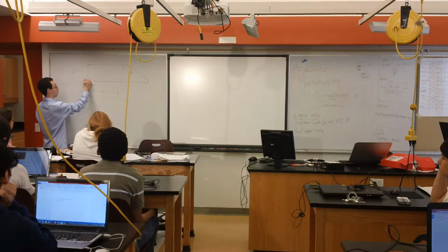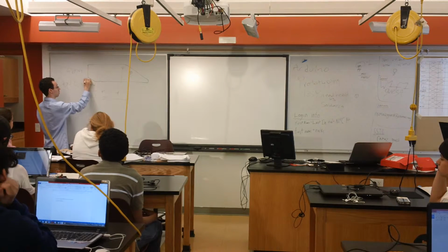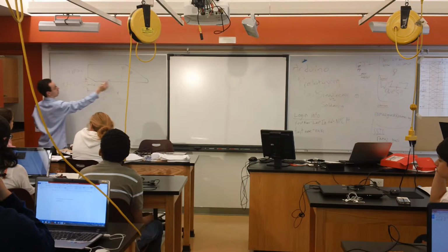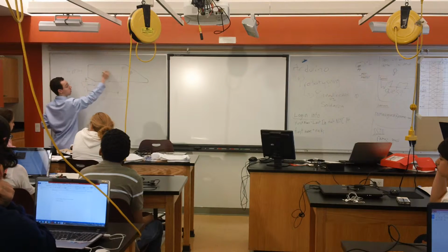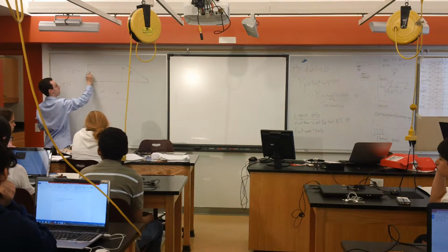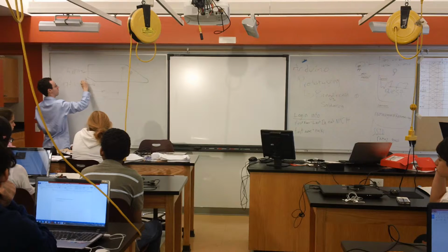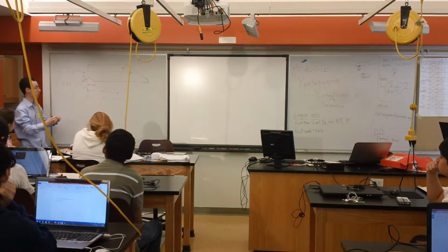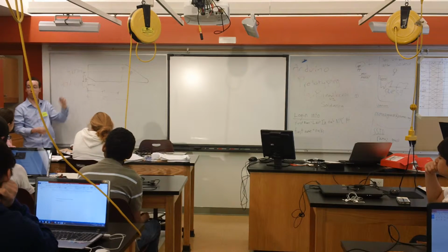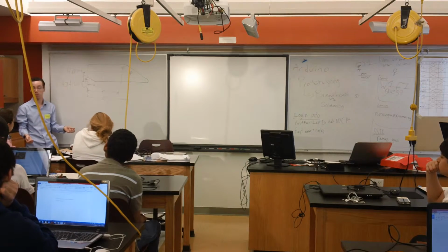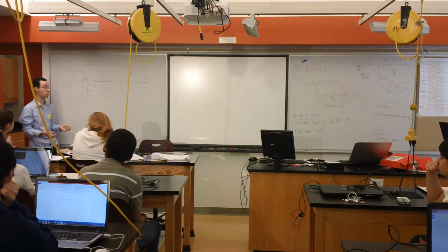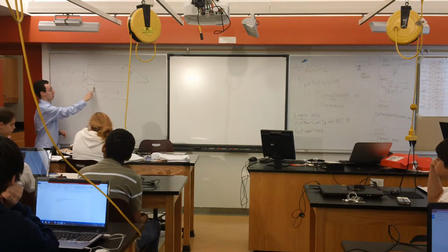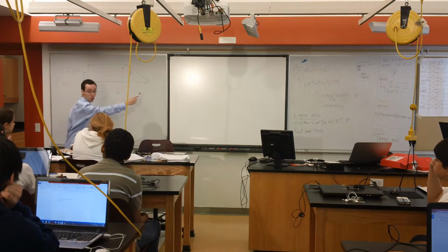I can say, okay. Now I can say this is 1/2 inch up, and then I guess I would start with this hole first, because I'm going in order. I would go, okay, this is 3 inches up, or whatever it is. Yeah, so you're basically showing x and y coordinates to an origin. That's all datum dimensioning really is. Chain dimensioning being, like I said, sort of a relative thing, where this is this far away from this, and then this is this far away from that, and then this is this far away from that.